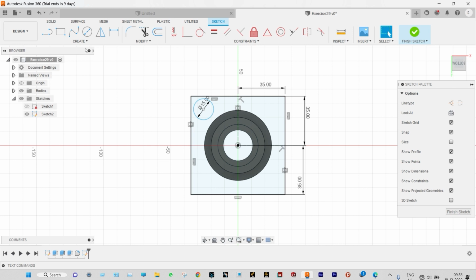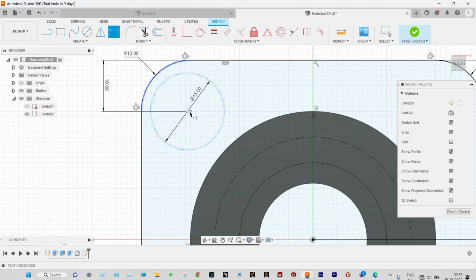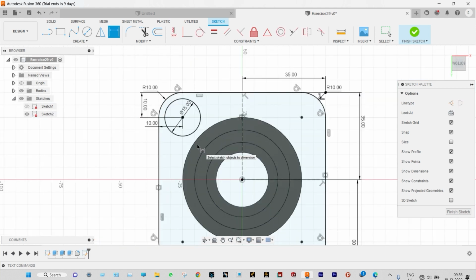Right, so starting fillet on the corners. This one will be having a fillet radius of 10 millimeter. Done. And the same thing to be provided here also. And again fillet to be provided at the extreme bottom side. We have provided 4 fillets of radius 10 millimeter, and the distance of this hole to be defined again. The distance of this circle from top horizontal line is actually 10 millimeter. Again the same distance from the vertical line is also 10 millimeter. Location of the circle is specified.